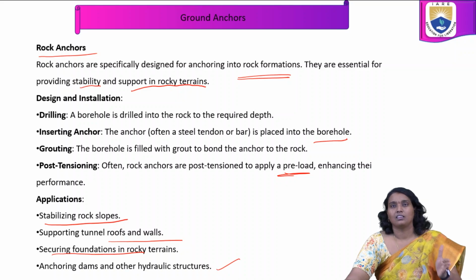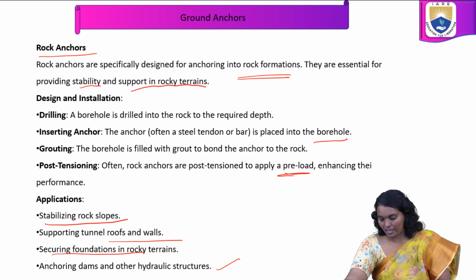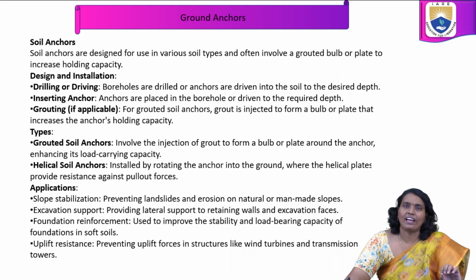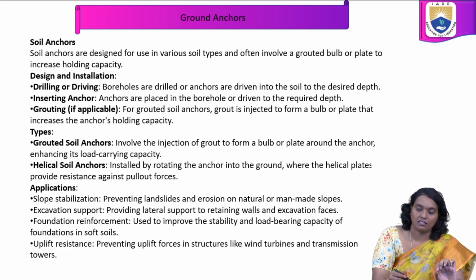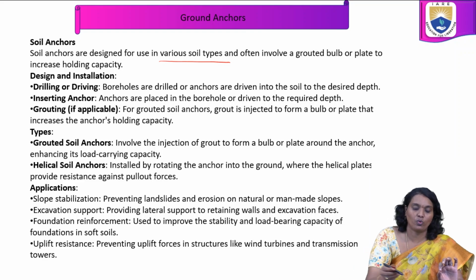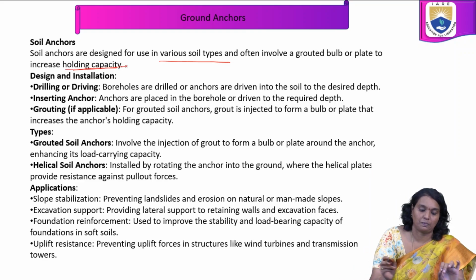These are the rock anchors, especially for rock formations. The next type of anchors are soil anchors. They are designed for use in various soil types and often involve a grouted bulb or plate to increase the holding capacity.